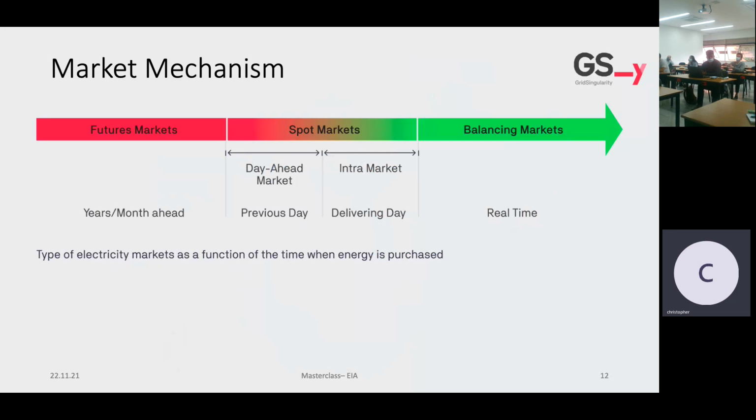One thing that is important in the software is that the simulation and the spot market in the end are divided into time slots. So if you're simulating one day, so 24 hours, those 24 hours will be divided into multiple time slots where each asset will try to buy or sell the required energy. The length of those time slots can be set as a parameter. Usually we set it to 15 minutes, which is based on the European spot market, but it can also be set to a length of 1 hour or even 2 hours, depending on the country.